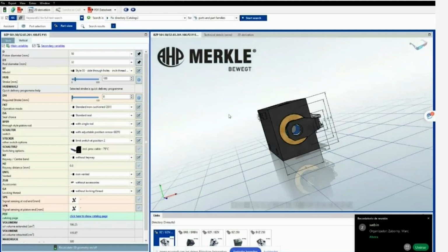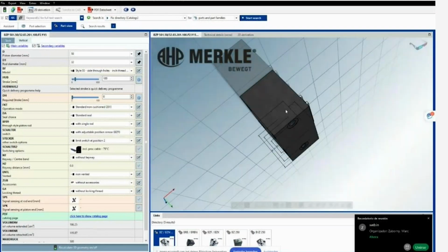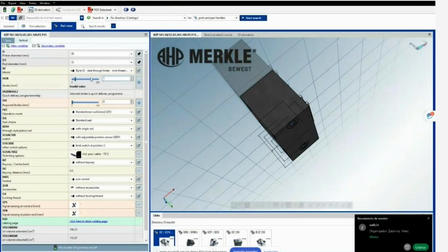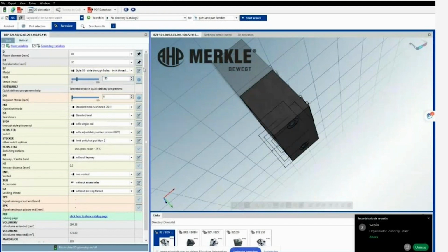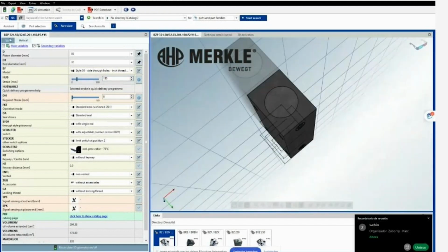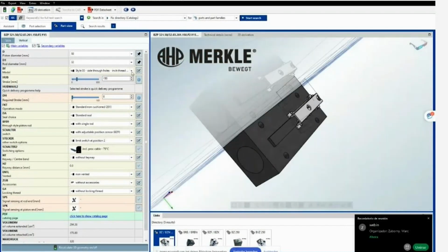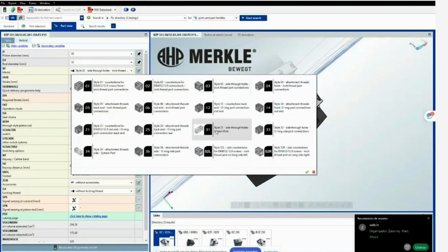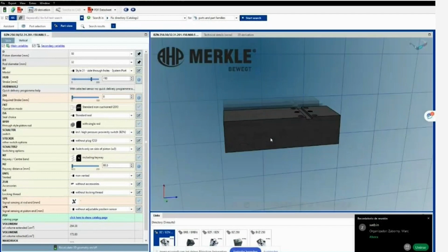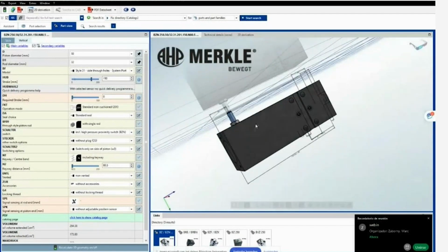So our block cylinders have three different kinds of capacities. 500 bar, where it has no rear cap. When it has the rear cap, as you can see here, if I change this to 150, it goes down to 320. But if I change this to a mounting mode that we call mounting mode 31, that I showed you in the videos, this goes down to 250.